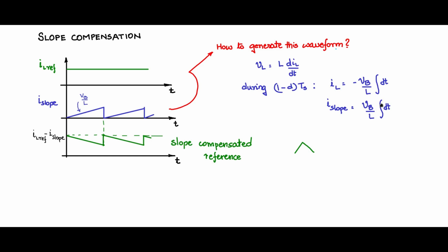So how do we obtain this current wave shape? How do we get this wave shape by implementation? What we can have is a controlled current source like this, and that controlled current source is connected to a capacitor like this, and let us say Cs is the capacitance, and then you can monitor the voltage VCS across here.